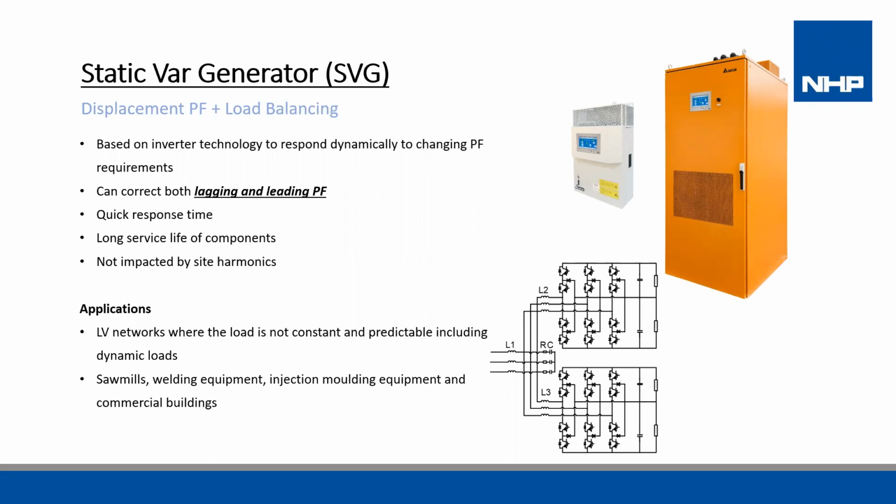up to 20 milliseconds, a long service life, typically about 10 years plus. Internal components also have a very long service life. There are no moving parts other than cooling fans and any other materials part of the enclosure assembly. SVGs are also not typically impacted by high harmonics.